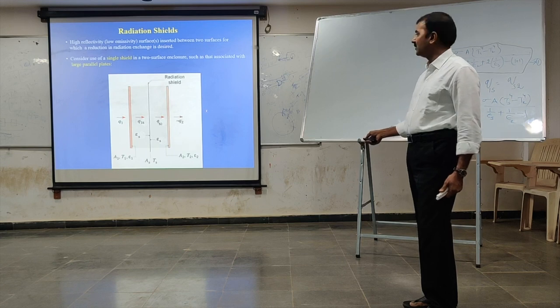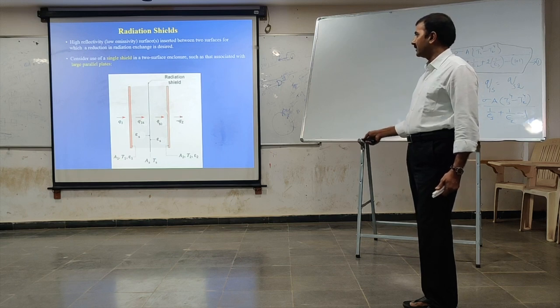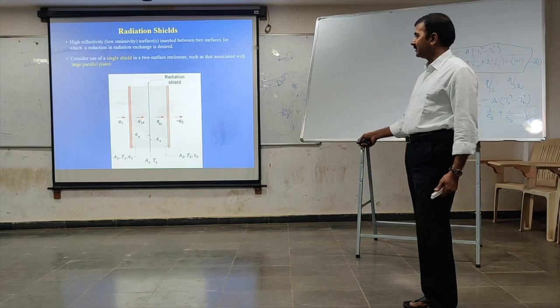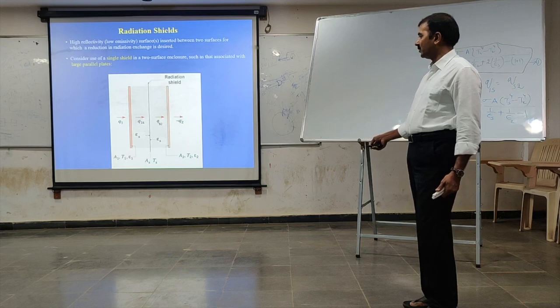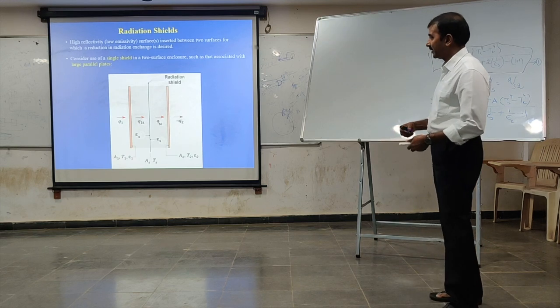That's the reason why. You need not even represent all these heat transfers. Just simply one plane, another plane, and then the sheet. Symbolically, to show that there is surface resistance on either side, sigma s. Then A1, T1, epsilon 1, A2, T2, epsilon 2. That's it. That much you have to represent.